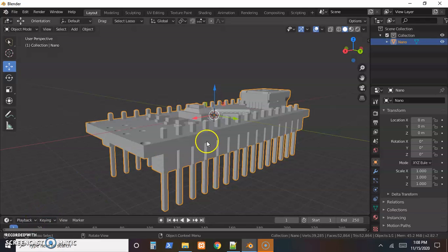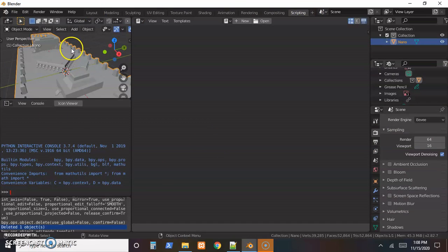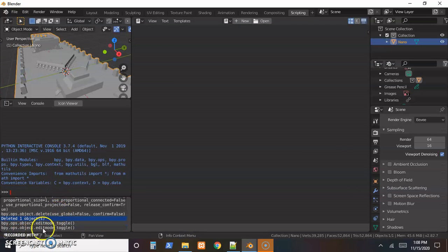And I have that script of materials, so we can bring that in. So up here in our tabs, we can go over to scripting. And if you're familiar enough with CAD to just type stuff in, there's a Python interpreter here, and you can type the instructions right in. And to learn them, you'll notice this little section down here at the bottom. That shows everything we do. So like when we select something, it gives the exact thing of what we're doing.